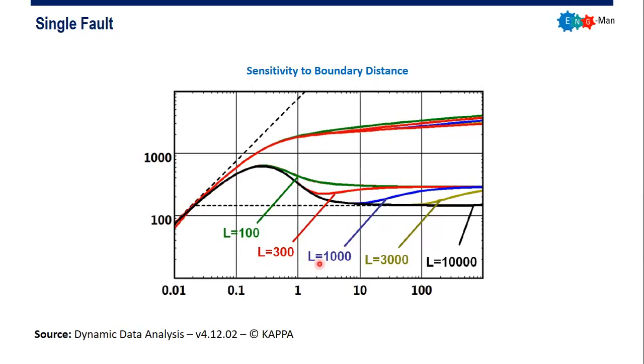If we have L equals 1000 feet, the first radial flow can be analyzed quite clearly, and then it will deviate, indicating a fault, and then we will have our second stabilized radial flow. And also for L equals 3000 and 10,000 feet.